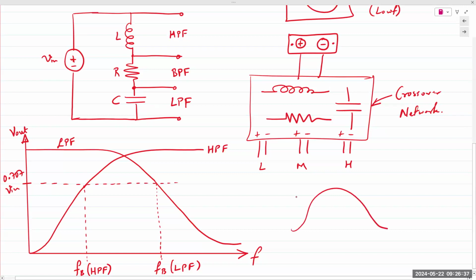So you have the high pass filter that has a cutoff frequency, you have the low pass filter that has a cutoff frequency. So that means if we design our filter, our resonant circuit, with the components, we can design a band pass filtering output for specific frequencies. If we choose the component values such, we can allow a narrow band or we can allow a very wide band.